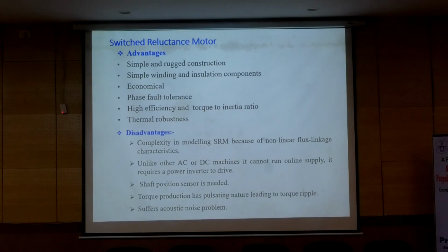So it is not that advisable, as in DC to DC converters. We need not go for very high switching frequency here, but moderately, an inverter grade switching frequency, like what we use in the case of VSI and CSI inverters for induction motors.